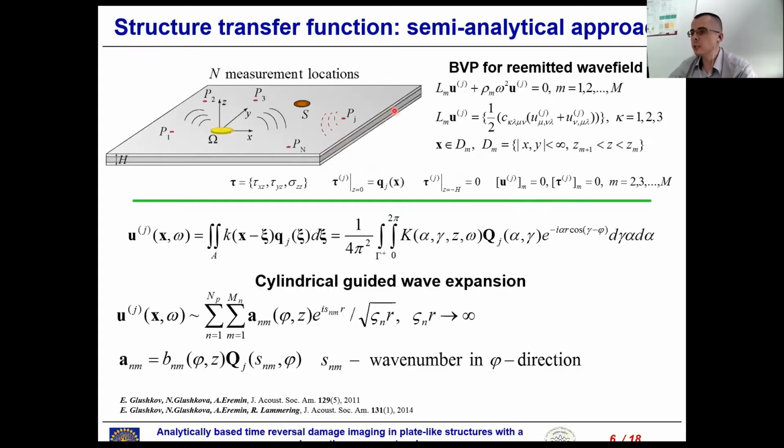We simulate each layer separately with a generalized Lamé equation for time harmonic motion. So we can assume that our plate could be either isotropic or anisotropic. We assume that we have stress and displacement continuity between sublayer boundaries. We assume that our plate is stress-free except the area where some loading is applied.